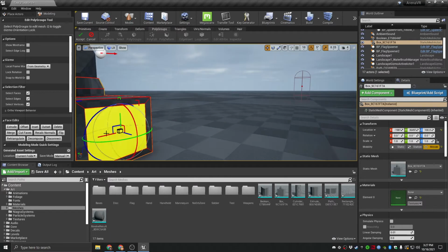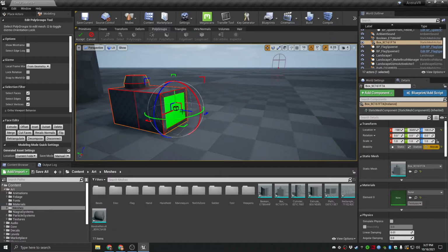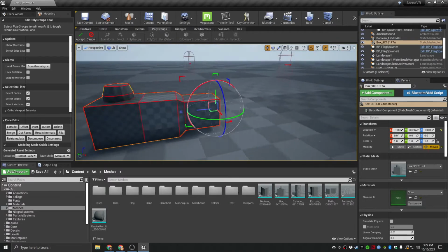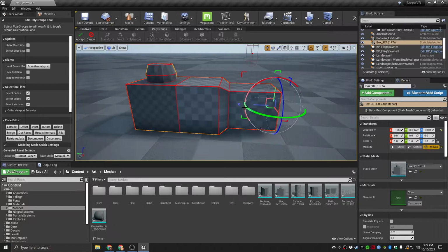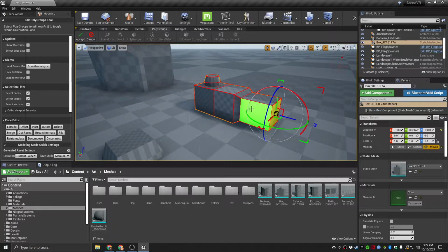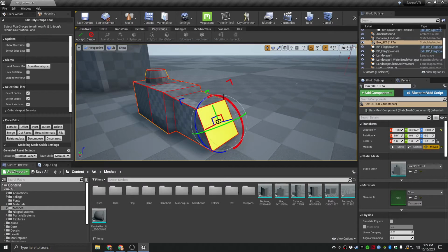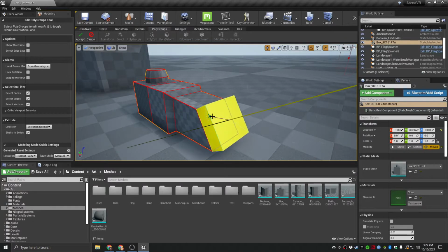There you go, and then you get an inset. From there you can either just pull it out, or start to extrude that. A lot of models are created in this way, actually. The basics of a model, someone might start by doing a lot of insets, outsets, and extrudes just to get the basic shape of something going. And of course, you can then rotate the face, and then extrude that.